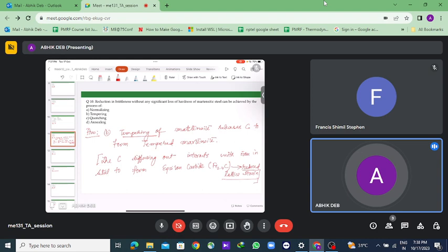Okay, sir. So for quenching and martensite formation, we can say it will be a diffusionless transformation. Is there any martensitic transformation which has diffusion? No, no. The tempered martensite is formed by the diffusion of carbon out of the structure, so it is a diffusion based formation. Tempered martensite is formed by a diffusion process only. Martensite is formed by diffusionless transformation. That's what I'm saying.